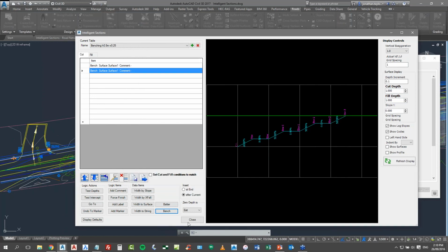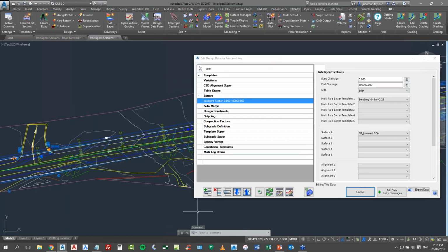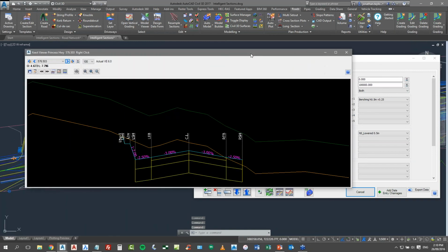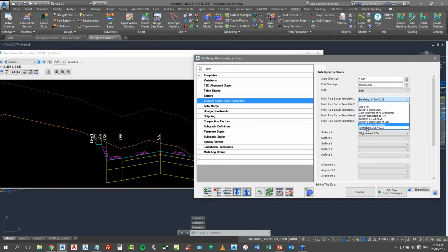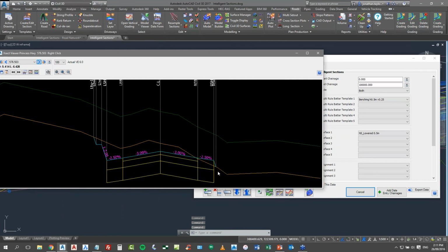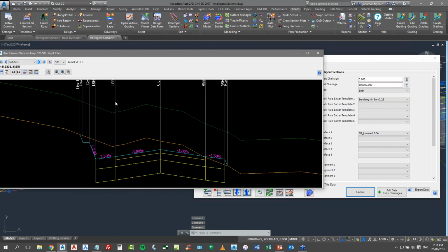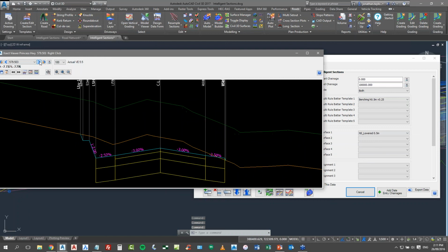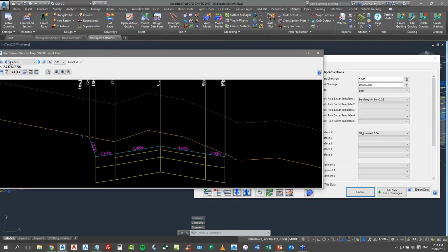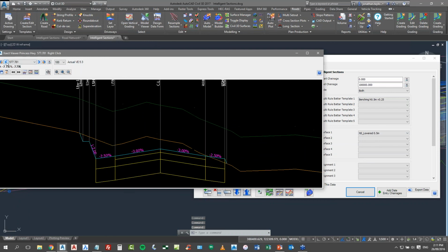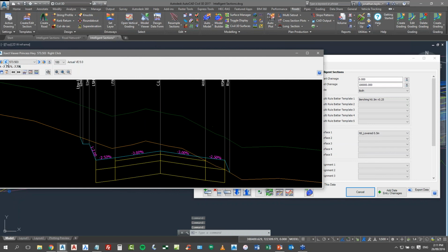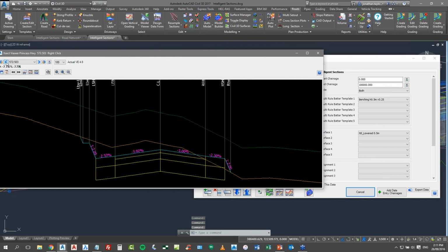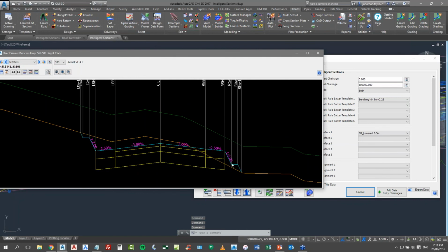Let's just check this is going to work. Let's click close. Let's bring up our cross section and just reapply it. There we go. So that's the trick with that. I wanted to make sure I showed you that. I know I haven't put anything in for fill, but essentially if it's below the sampled surface in cut and the surface it's referencing is below the code as well, you need to add in that other option, which is why it's produced that for us there.